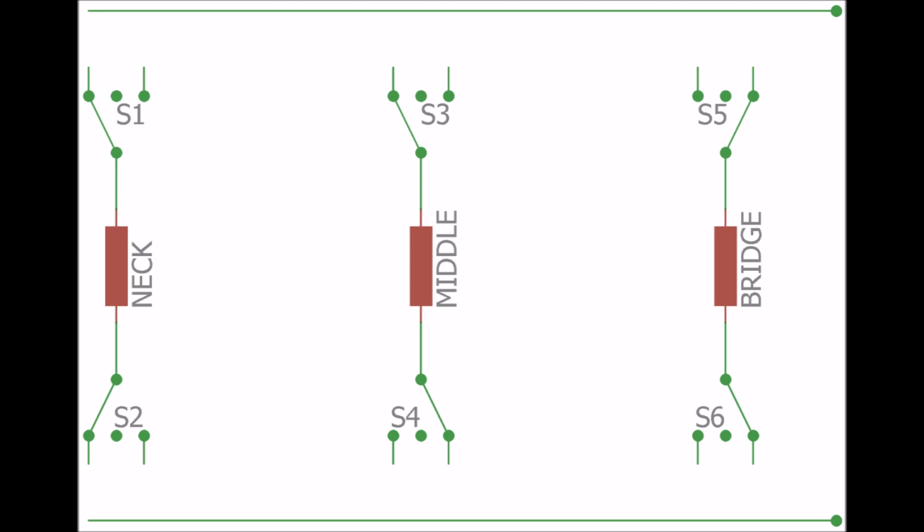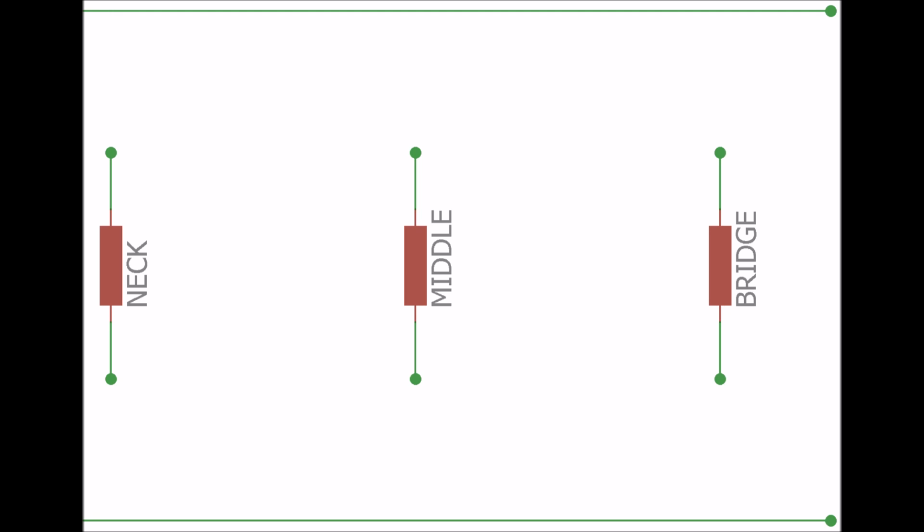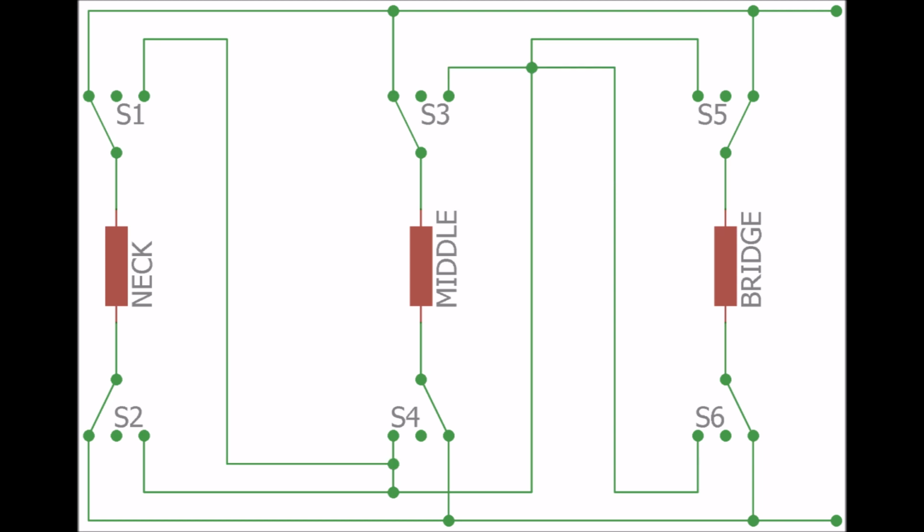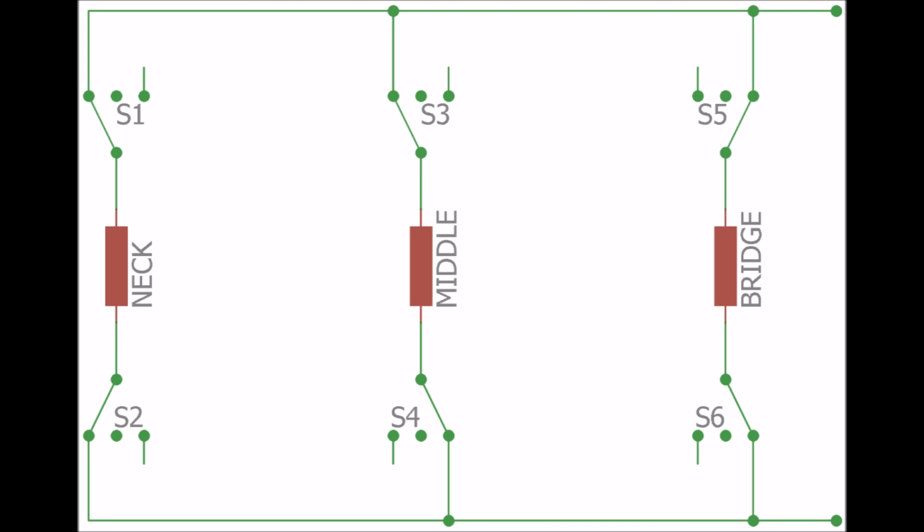For the meantime, to simplify tasks, a way must be provided to turn off a pickup when a combination connection has less than 3 pickups. A separate switch for this purpose can be added, or just have it as an integrated function in the SPDT switches, as a center-off position. There are two approaches in conceptualizing the circuit diagram: 1, the ground-up approach, or building from the basic connections and progressing to the compound connections, and 2, the top-down approach, or forming the compound connections initially, then these are broken down to the simpler connections.